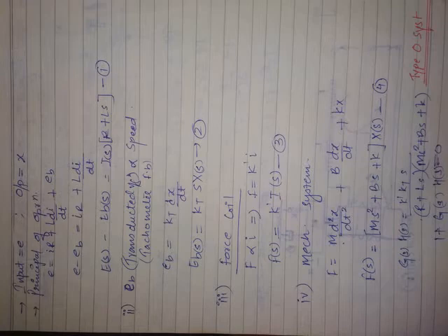Because we are having VA minus EB, you have to take one more summing element and signal to this summing element is EB. The transfer function is 1 by RA. Output is IA of S. This is going to KT. Output is TM of S. This is driving the load. The load is 1 by Js square plus Bs. Output is, this is through gears, it is becoming C of S.